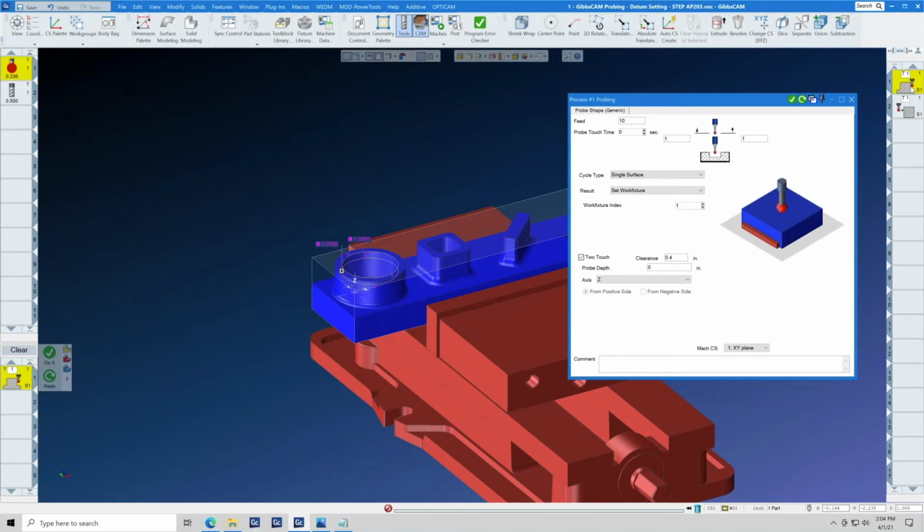The next thing that we'll talk about is to shorten manufacturing lead times. Because we are no longer interrupting the machining process to either reach inside of the machine and measure something and then type a number in and possibly type it in wrong, we're going to let the probe do this for us. The probe is a very accurate measuring tool.